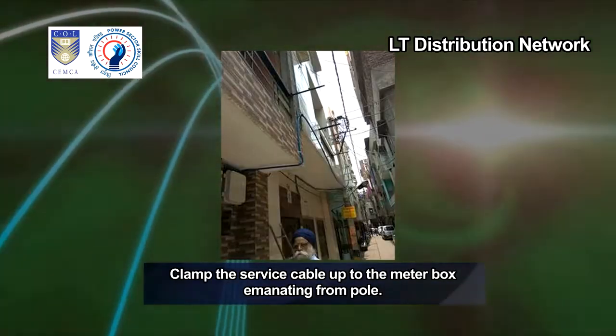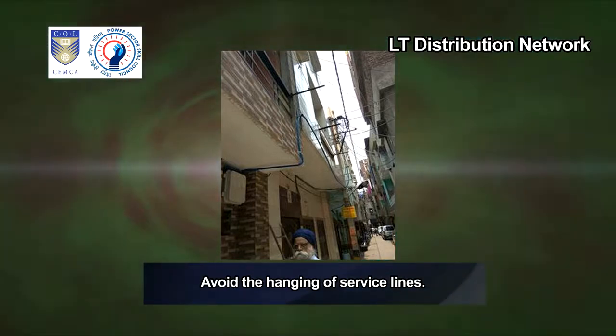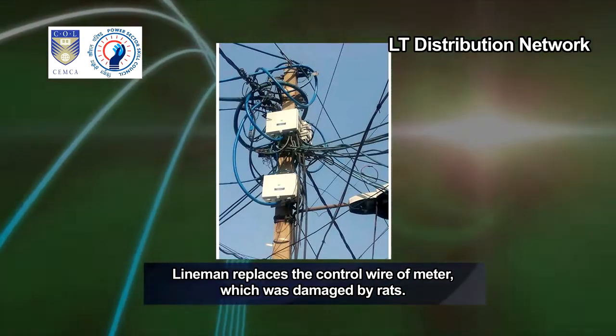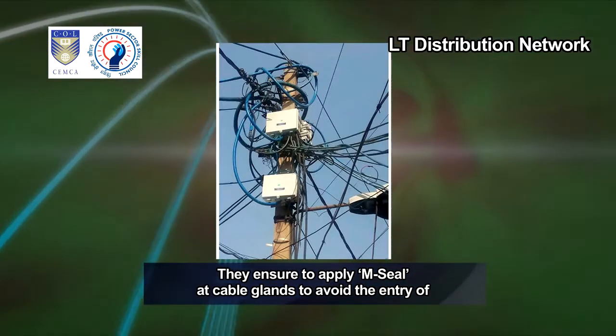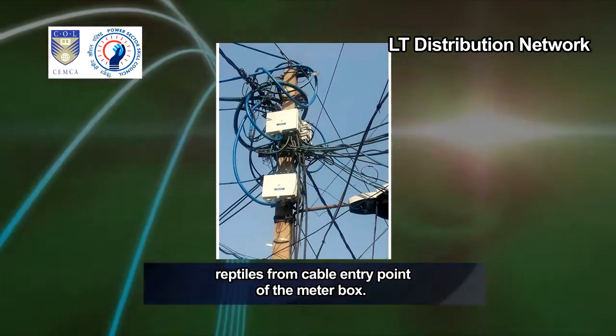Clamp the service cable up to the meter box emanating from pole. Avoid the hanging of service lines. Lineman replaces the control wire of meter, which was damaged by rats. They ensure to apply M-seal at cable glands to avoid the entry of reptiles from cable entry point of the meter box.